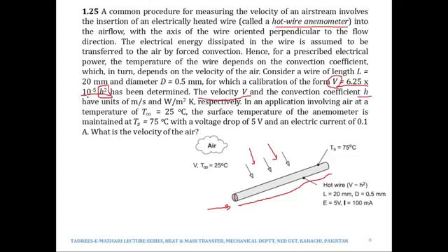6.25 times 10 to the power minus 5, there may be some constants in it. Number two, if this is a statistically developed equation using a tool such as regression, those equations may not necessarily be dimensionally balanced all the time. So kindly do not get bothered with the question of how h square can be reduced to velocity. Of course q is equal to hA delta T would be dimensionally balanced, but those equations which are developed using some mathematical or statistical techniques may not be dimensionally balanced all the time.